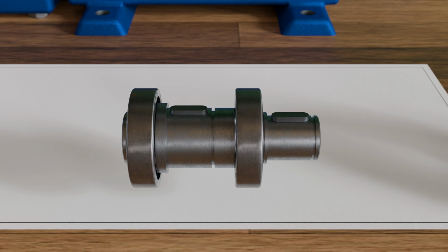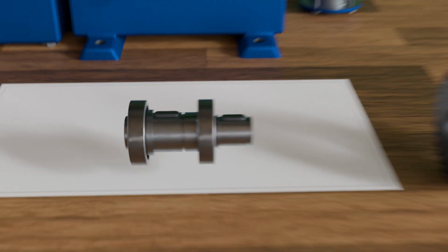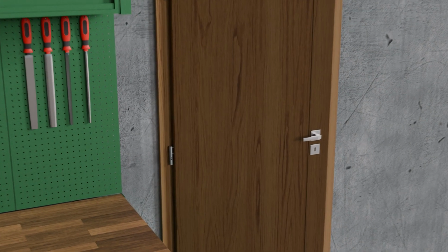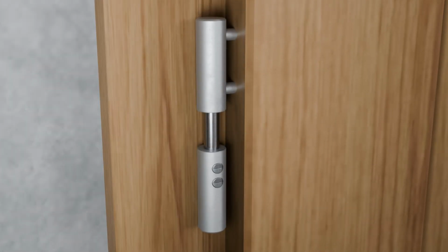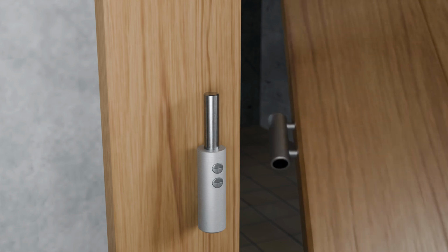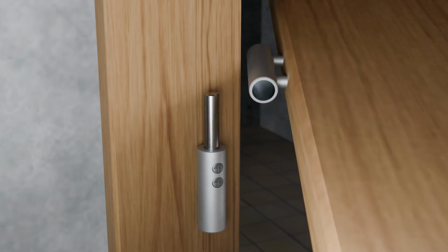In a plain bearing, the moving component slides directly on the bearing surface inside the housing. A common everyday example of a plain bearing is a door hinge. There, a pin slides within a bushing, allowing the door to rotate. The characteristic feature of a plain bearing is the sliding friction that occurs between the contact surfaces. To minimize this friction, lubricants such as oil or grease are often used. Plain bearings have a simple design but are sensitive to dirt and often require more maintenance than other types of bearings.